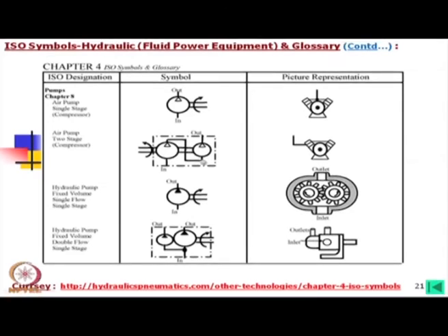This is, you can see, a double pump, that means it is basically a compressor, not a pump, you can say this compressor. In that case, two stage, in the first stage there is a certain raise of pressure, and in the second stage it is further raised. In a single stage, if you like to use a single compressor, that will be huge in size. Instead of that, in two stage we can get the desired pressure of the air or gas.